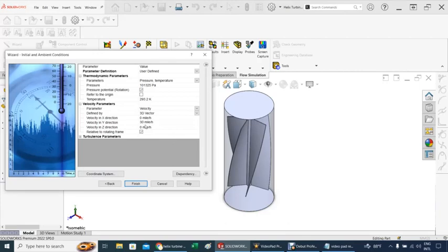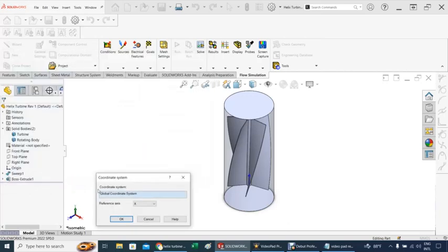That's a strong wind. Now, the coordinate system, you see, is pointing to the x direction. So this guy will rotate in the x direction. That would be weird because that means there's an axle crossing this, and this is spinning like this. And it's not spinning in the x-axis. It's spinning in the y-axis. So be careful with the global coordinate system.